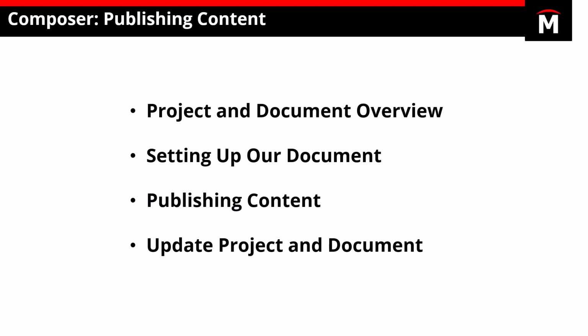Publishing content in this way, we're utilizing high resolution images for our Word document. That's going to export them all at the same time. And even when we go to update our project with design changes, we can republish our views with the appropriate changes. And from there, we can simply update the links in our document. Remember, the edit links to files is one of those items that will allow that to happen, as well as inserting your pictures with insert and link to file, as opposed to just inserting.